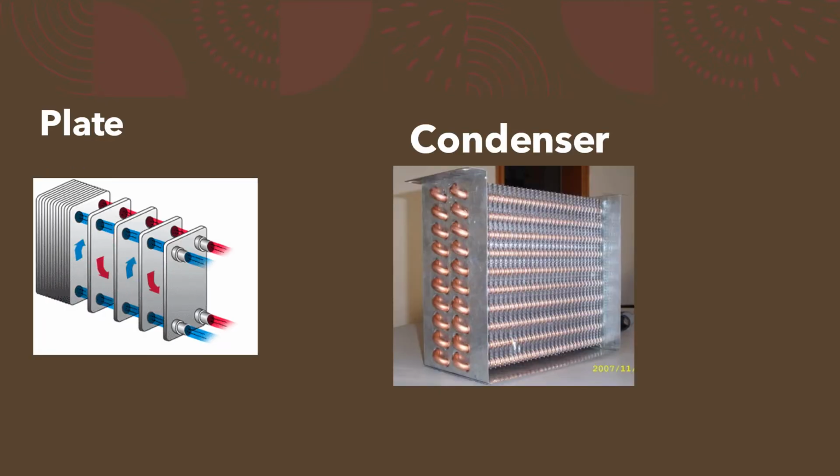The third one is a plate heat exchanger. This is made up of many thin metal plates to cool the liquid. It can be configured to allow the liquid to pass through multiple times. These are generally used in HVAC applications.